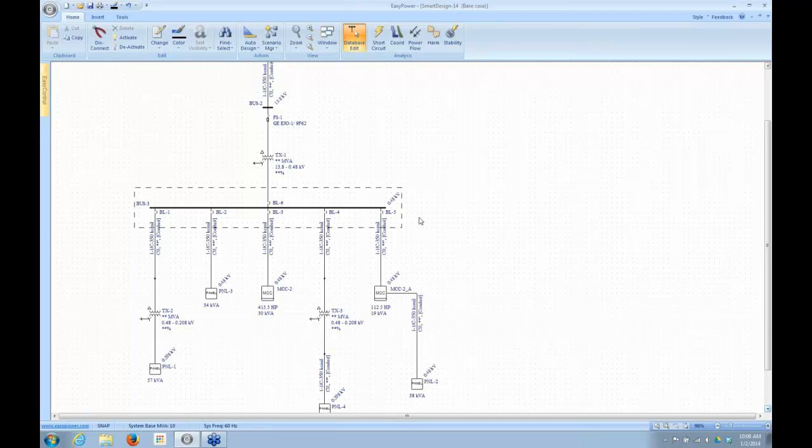It works the same way you would attempt to size something or verify your sizing: by looking at the downstream loads, collecting all these downstream loads and aggregating them up into the main bus, so you can size that and the main breaker and the transformer.